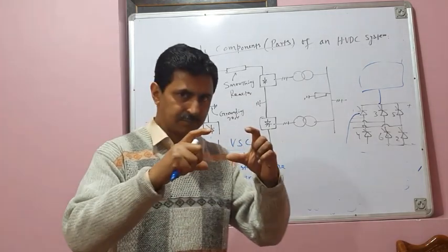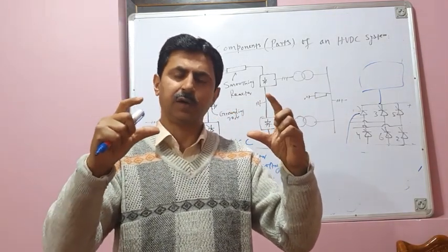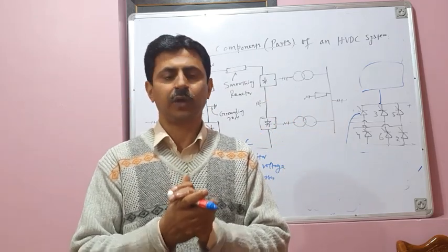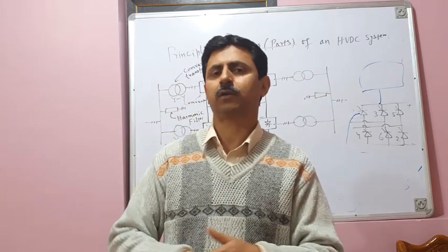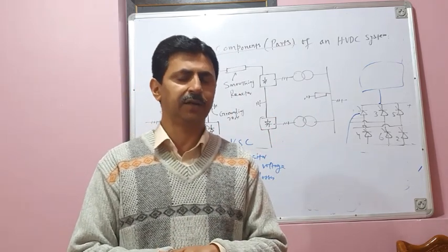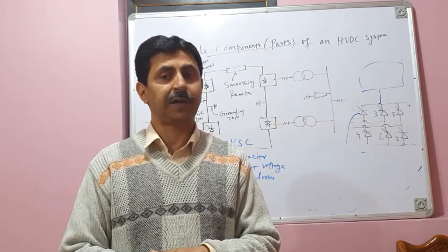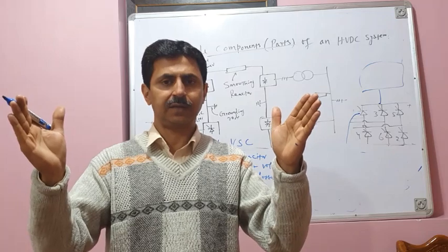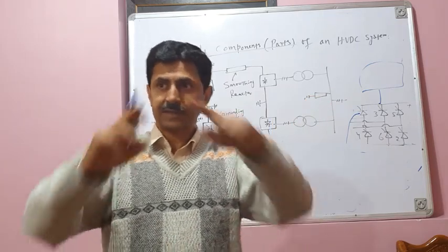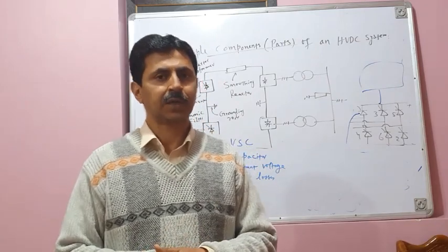The reactor, when I say inductor, it's not a few millihenry, it may be of the order of 1 or 2 henries. And when I say 2 henry, if you visit our power electronics lab, we designed a few years back 5 millihenry or 6 millihenry inductors, they are of this size. Imagine 5 millihenry is of this size, what will be the size of 2 henry? Maybe the size of this room, very large in size.